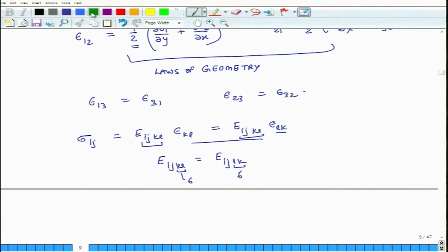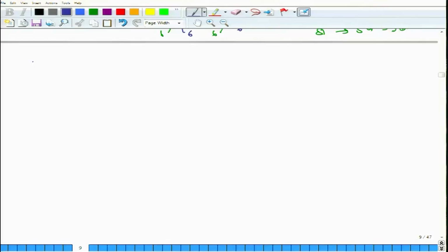And in our original discussion, because of stress symmetry, these have 6 different possible configurations. Because of strain symmetry, these have 6 combinations. So, the number of constants goes down from 81 to 54 to 36. So, instead of having 9 equations, we have 6 equations involving 6 stresses, 6 strains and a stiffness tensor which is of dimensions 6 by 6.